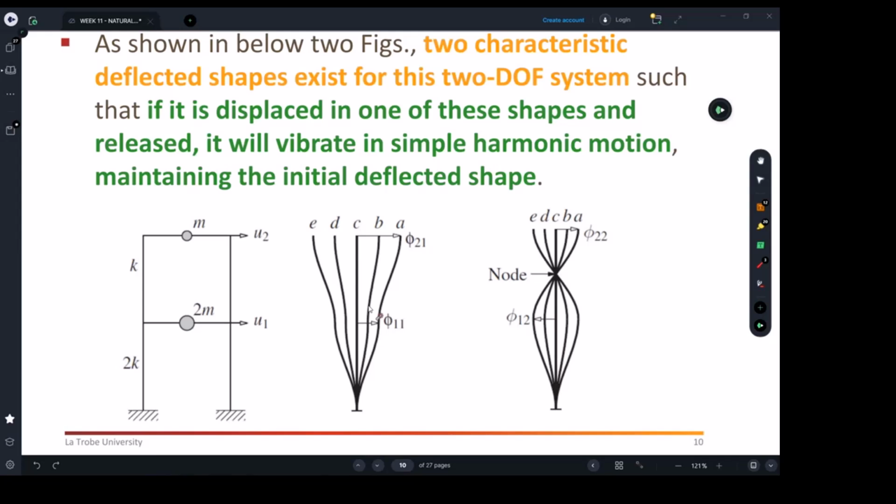Now, in your RCB building, if you ask the software to give you 30 mode shapes, it will give it to you. Why? Because there are always walls which are moving independently of the building. Whatever we did, we can't avoid this 100%, because the software is actually building a matrix for each wall, for each column, for each slab. So there are always mode shapes, even for the floors themselves. The floor itself has its own mode shapes.